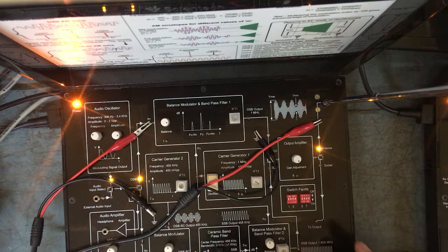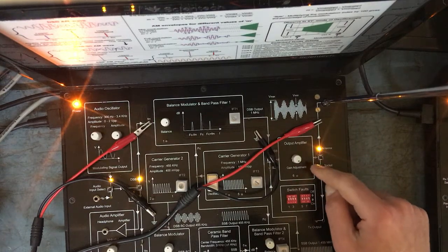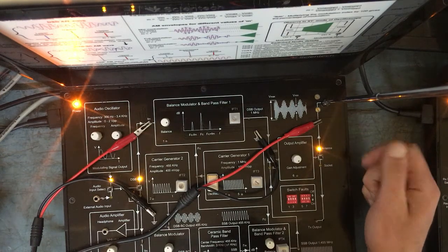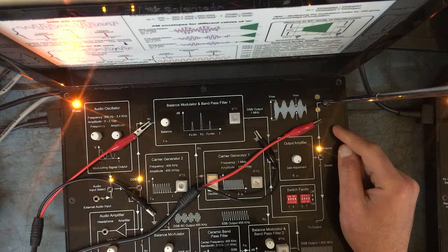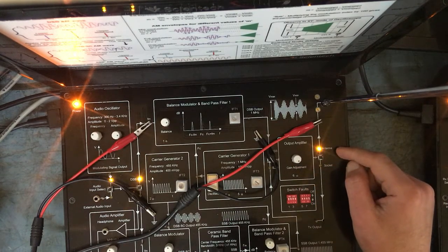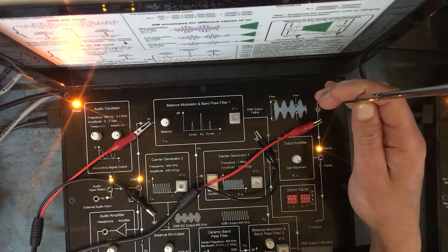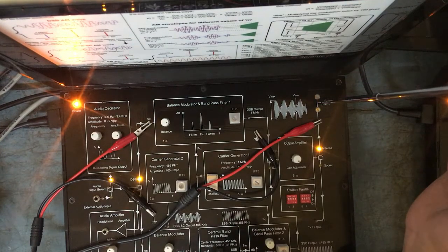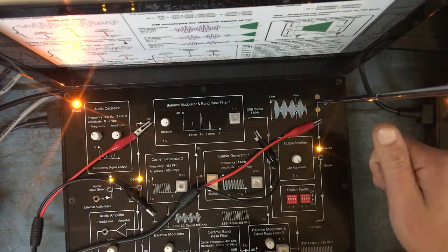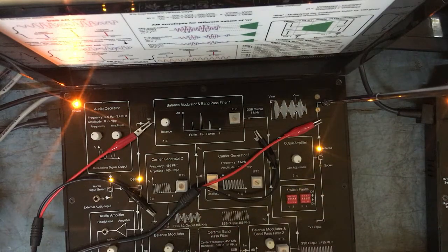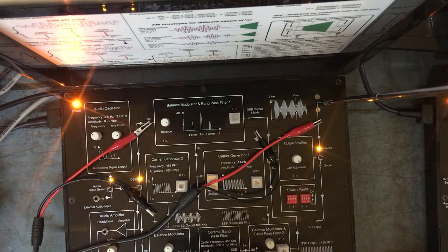Okay, so after that, the amplifier output from the antenna, because we'll be transmitting the signal wirelessly, would be noted, and that should be the AM signal, but in an amplified mode. In order to check whether the antenna is transmitting, we can just hold the antenna and we'll see the loading in the signal happening. So that would confirm that our antenna is transmitting the signal, and the signal being transmitted is almost 1.3 kilohertz.